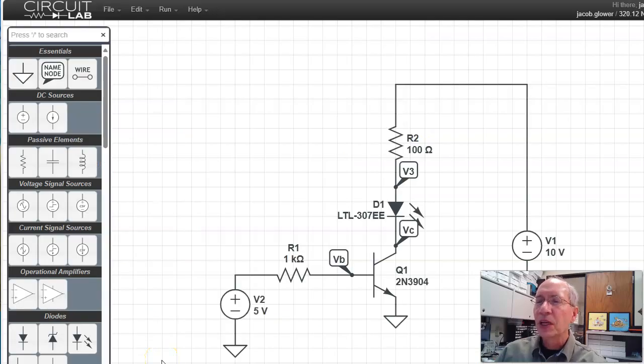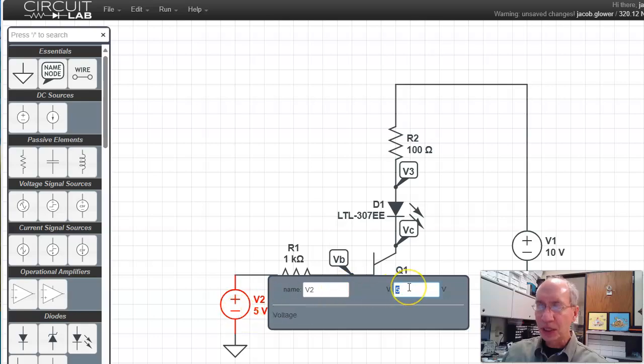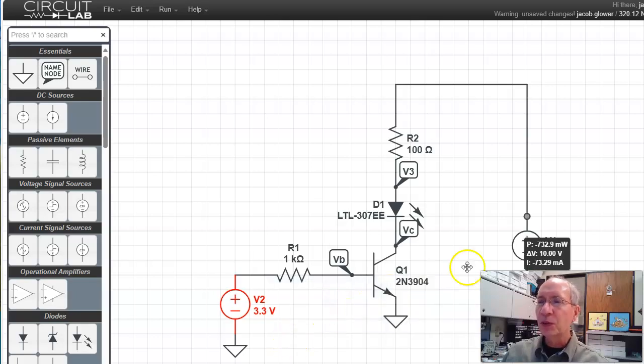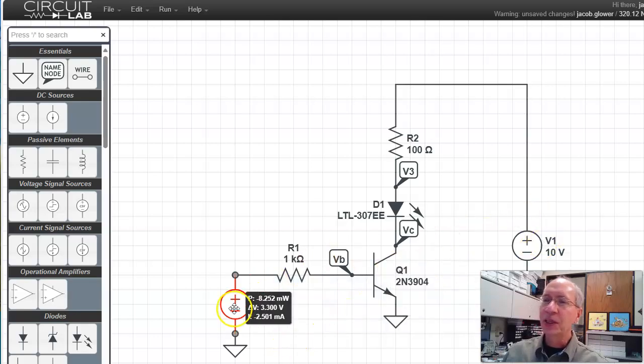So for example, if I want to verify that my transistors have 20 milliamps flowing through them, I've got a microprocessor, possibly that's turning it on and off. CircuitLab doesn't really simulate microprocessors, but what you can do is say this is a PIC, or Raspberry Pi Pico. It's either 0 volts or 3.3 volts. Apply 0 volts, make sure the transistor's off. Apply 3.3 volts, make sure it's saturated. So this is more DC analysis.